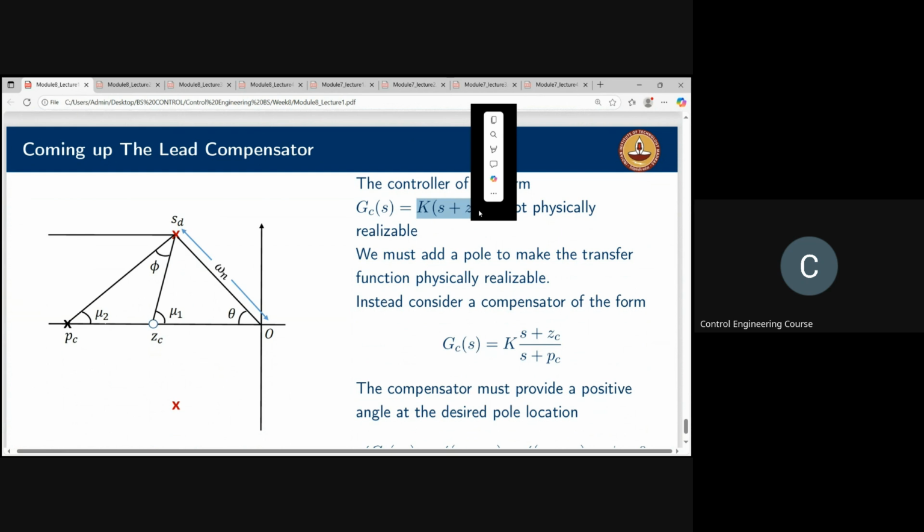If you differentiate sine omega t, what do you get? Omega cos omega t. When omega is really, really high, what will happen to the magnitude of the derivative? It will blow up, right? Yes, sir. So a pure differentiator is very sensitive to high frequency noise.